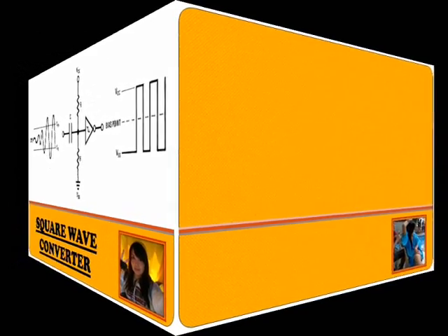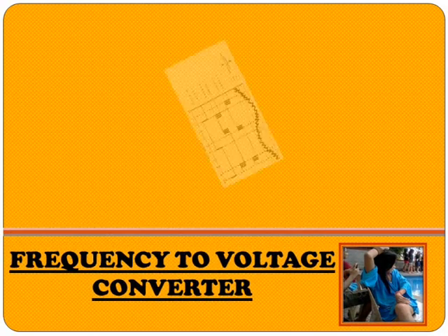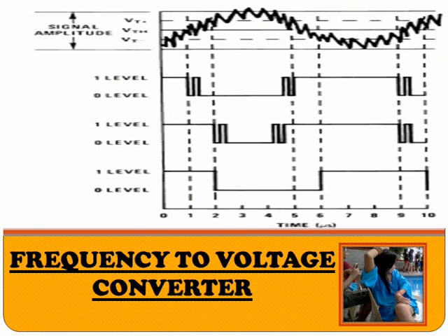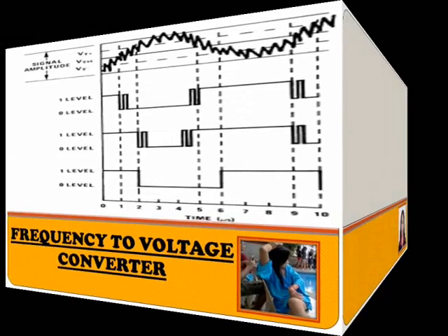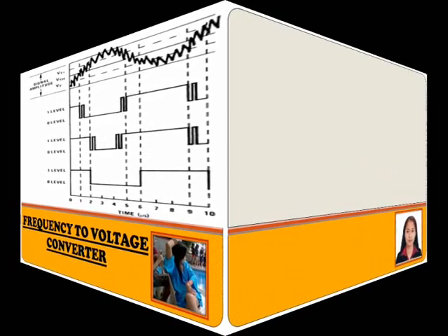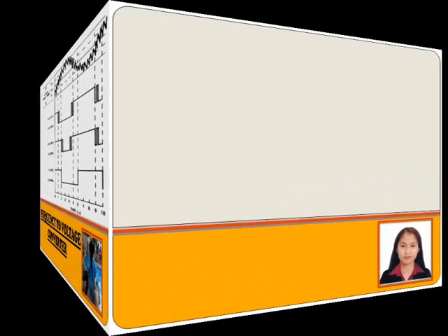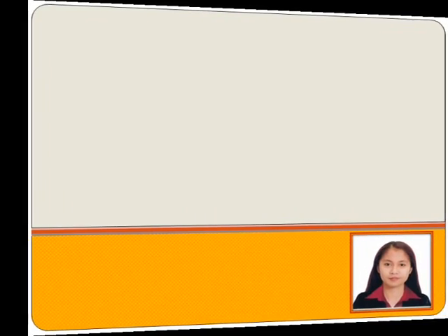We see a frequency to voltage converter that accepts many waveforms with no change in output voltage, although the energy in the waveforms is quite different. It is only the frequency that determines the output voltage. Since the output of the CMOS-Schmitt pulls completely to the supply rails, a constant voltage swing across the capacitor C1 causes a current to flow through the capacitor dependent only on frequency.